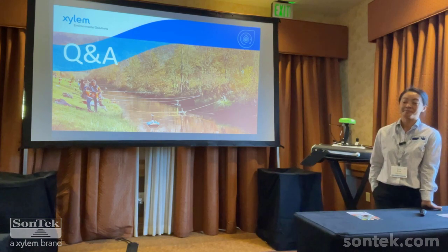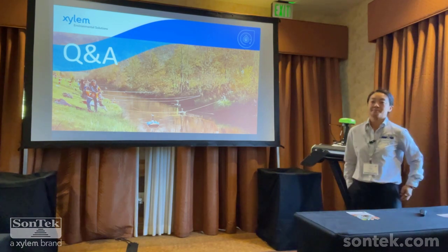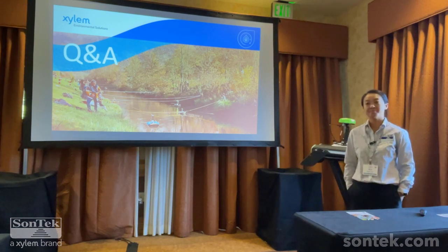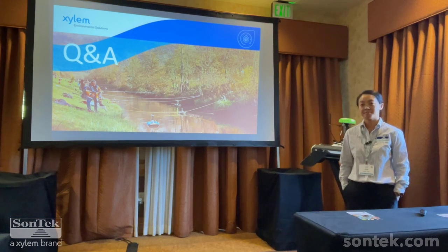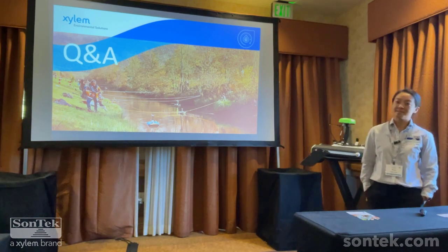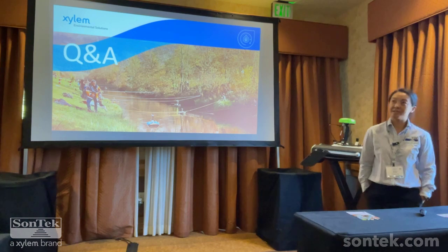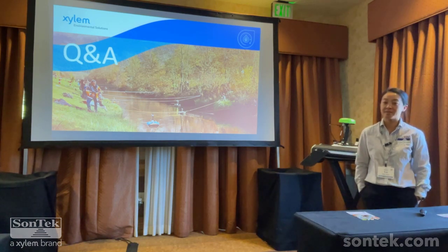And I've seen various ways of calibrating the compass. We have an agency that has a tripod they set up, set their ADCP on, and then rotate it on that. And I've asked them about the metal in the tripod. Would that produce issues in compass calibration, and would you know it if you were getting issues with calibrating your compass if there was metal? Yeah, it could.